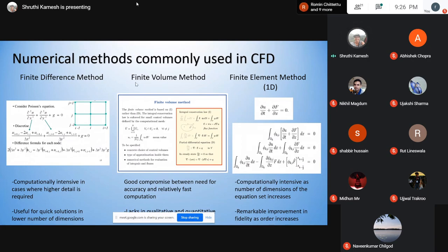One thing with finite element is that you can get increasingly high order solutions, which is that your solutions become more and more detailed as your order of solution increases, because I'm including more variables and increasing the space at which I make particular approximations. So ideally you would expect that the accuracy increases.